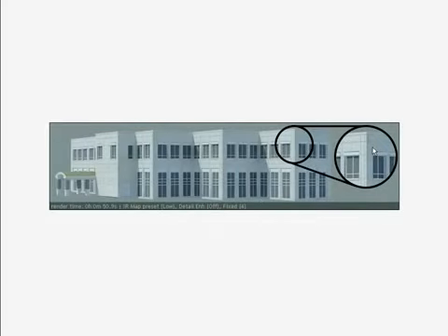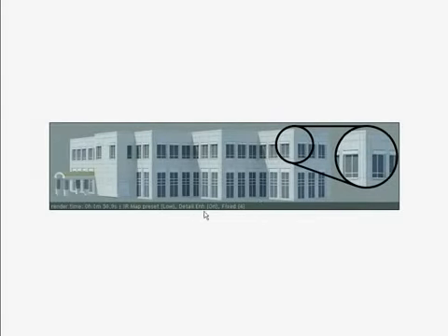And now if I choose the detail enhancement option under the Radiance map and render it again, my render time increases again, but you can now see some improvement using the detail enhancement that you couldn't before. And now this image sampling increase brings out this detail enhancement.